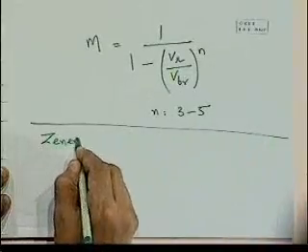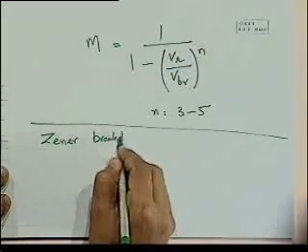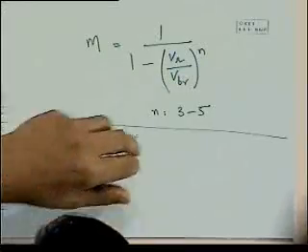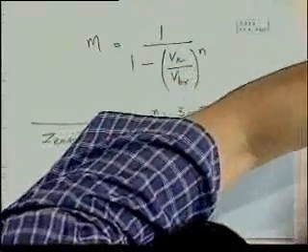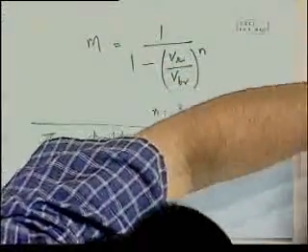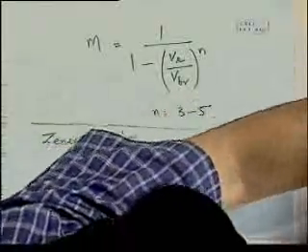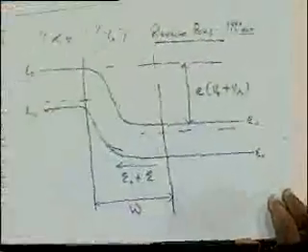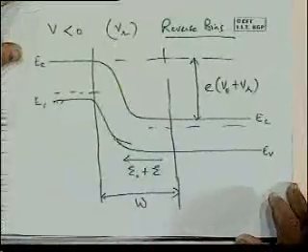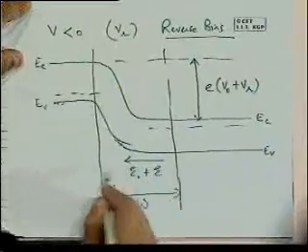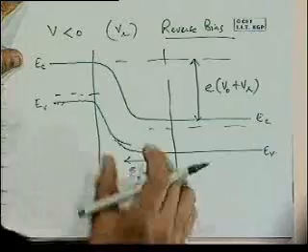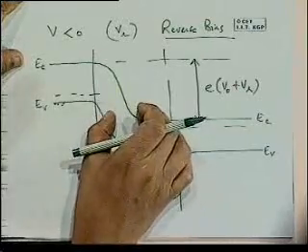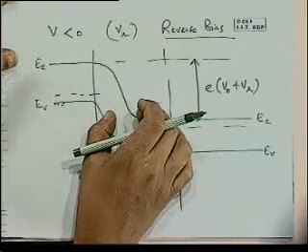And very quickly, the Zener breakdown. I'll come back to the figure that I drew to simply make use of it and conclude here. Namely, if we have enough of a voltage in a heavily doped diode, and the doping is heavy, we recognize that the depletion layer width is small. So W is rather small for a heavily doped diode.